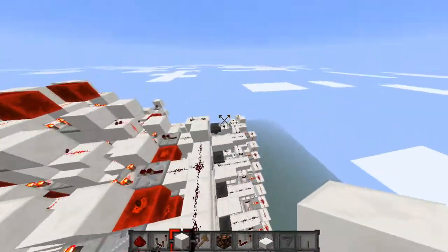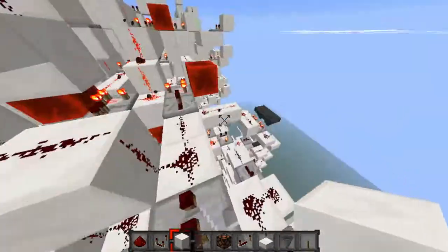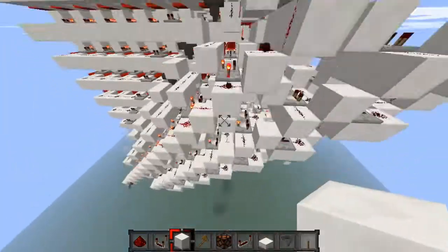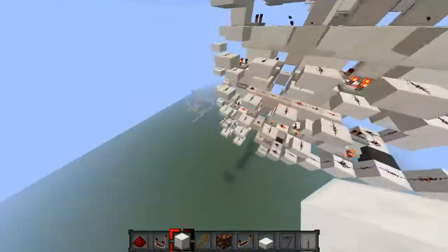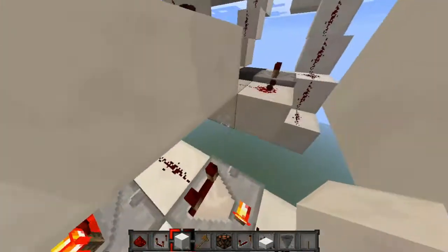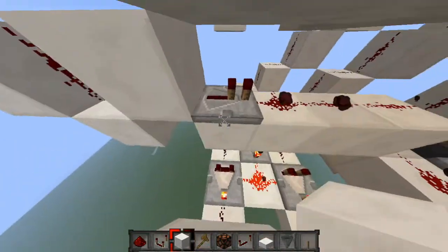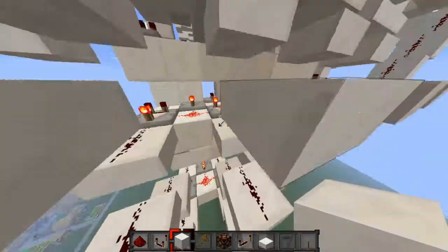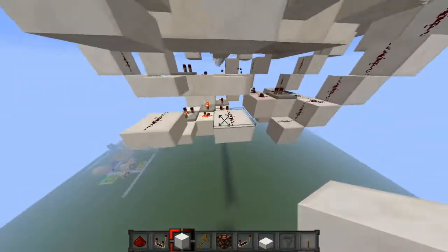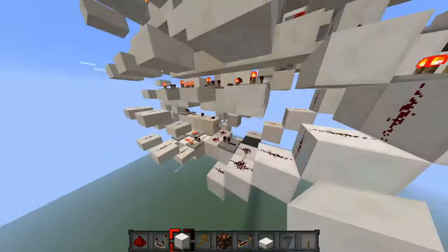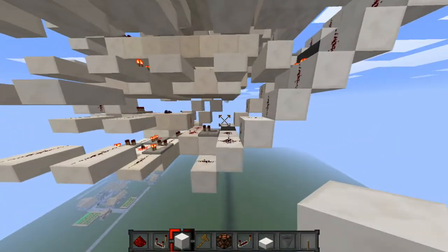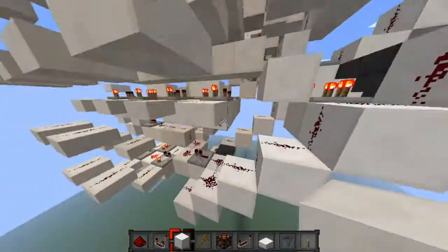On the other hand, if the bit number makes it so that it can't go to the most significant bit, it could only go to this bit, what we're going to do is we're going to use the barrel shifter to shift it in the opposite direction so that it comes down to here, and when it reaches down here, we're going to basically just make it so that all of the bits except for the least significant bit are all off. And that way that bit will be isolated, and when we do that we can cover every single situation. So how exactly do we make sure that all the other bits are off?